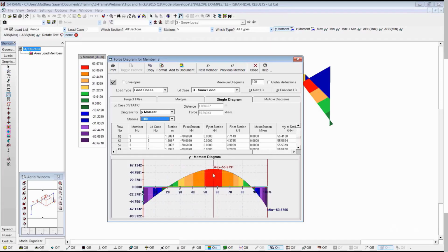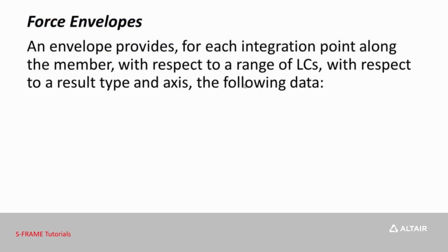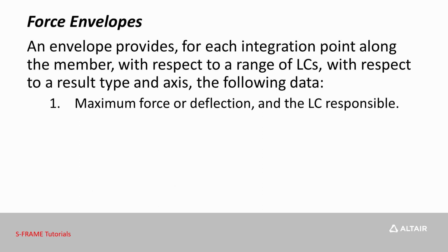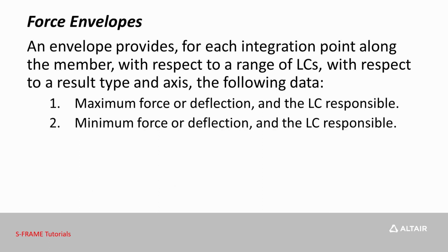Now we know a number of you are using force envelopes already, and we hope to answer some of the frequently asked questions about this tool. So when working with force envelopes, essentially they give us several different integration points along the member, and we're able to look at the maximum force or deflection and the load case that's responsible for that, as well as the minimum force or deflection and the load case responsible for that as well.